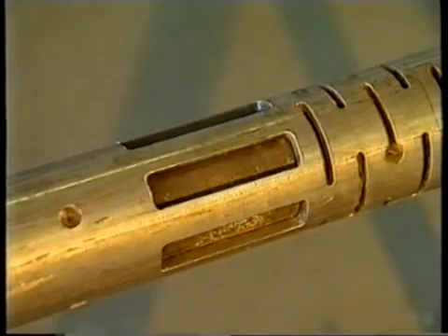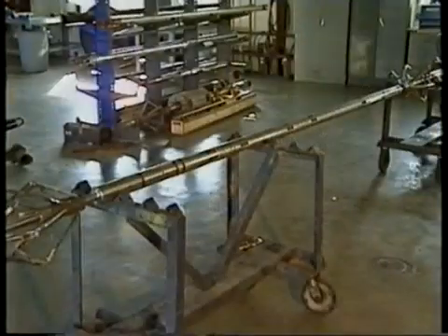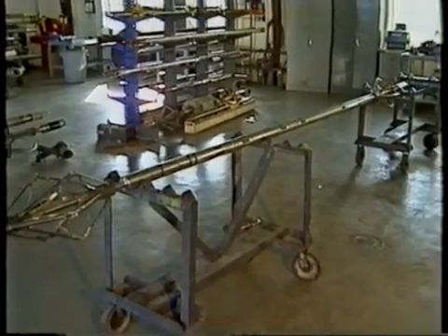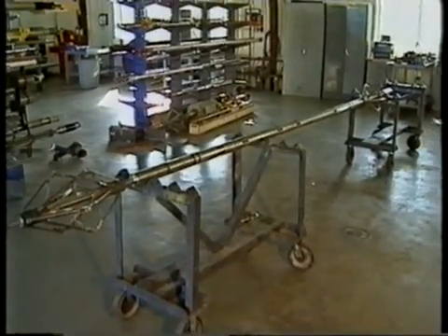Note also that some tools, like Schlumberger's fluid-compensated CBT, incorporate technology that automatically provides readings in decibels per foot. Your manual also discusses the differences among the following: the typical CBL, the well-bore compensated CBL, the pad-type CBL, and the pulse echo CBL.